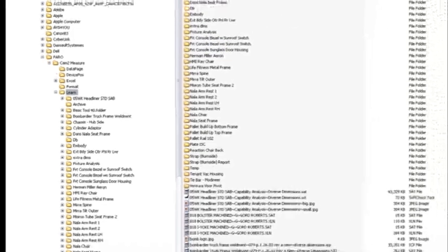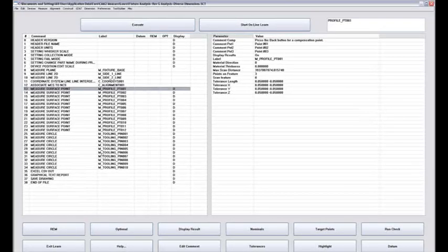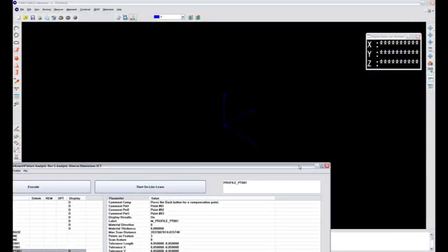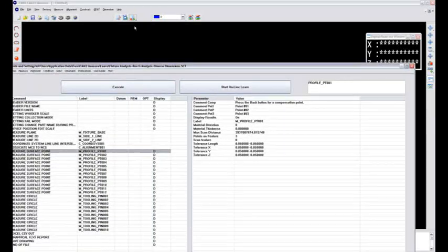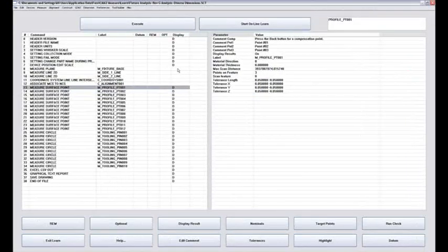Now I'll run back out to that SoftCheck tool. So just remember, when you save your SoftCheck tool, Faro is going to make a file that's known as an SCT for SoftCheck tool, and it needs a foundational file that runs in the back known as the SAT, and it'll have the exact same name. In fact, if I pull this out of the way a little bit, there's an SAT file running in the background there. And notice up top there, it says it's untitled. But what it's actually doing is it's creating a file that's an SAT file with this exact same name, and it puts it right in the Learn directory.